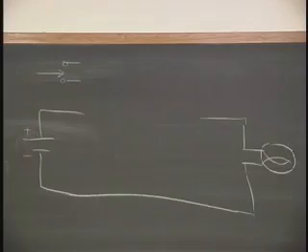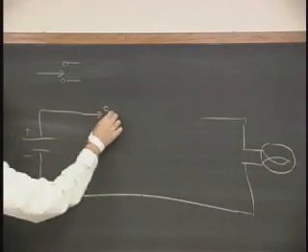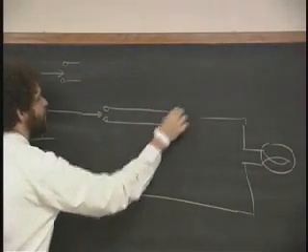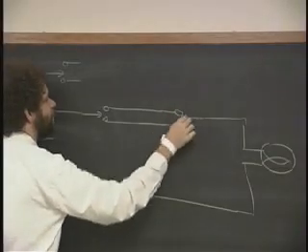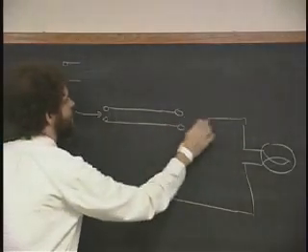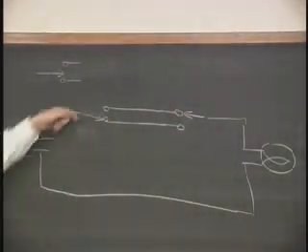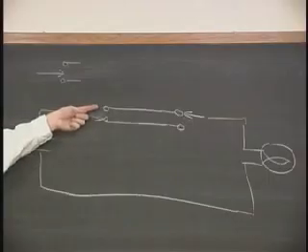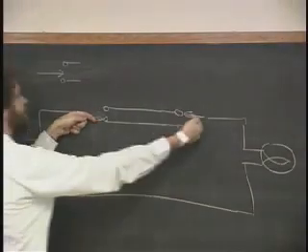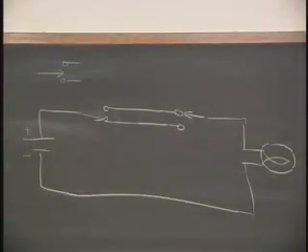Anybody want to take a guess? And there's a switch at the other end, pointing back. It actually doesn't matter if you cross the wires or not, but the switch at the other end is the right answer. It looks like that. So let's say this one is up, and this one is down, and the light's off, but if you turn this one up, then the light goes on, right? But if you don't turn that one off, you turn this one on, then the light goes on. Whichever one you switch, the light will change from one thing to the other.